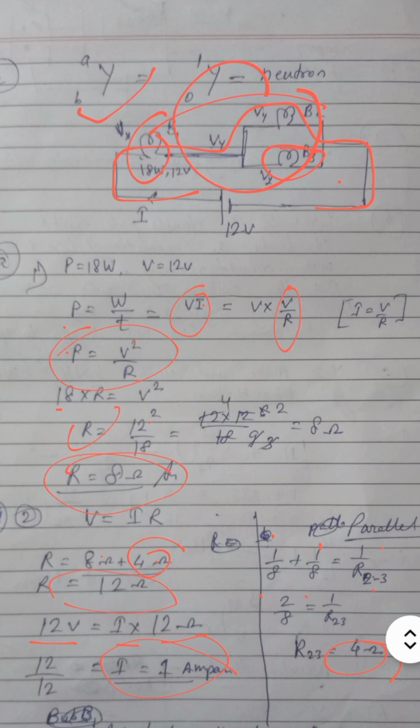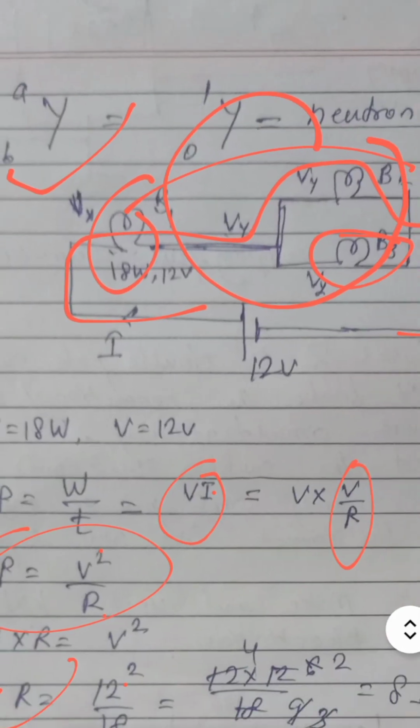So let us assume first what happens to the voltage. Here in series the voltages are V1, and here in parallel they have similar voltage V2, V2. So if we remove the bulb B3, the voltage here remains unaffected. It will remain V1 only, and here it will remain V2 only. So voltage does not change. So the brightness will not change.